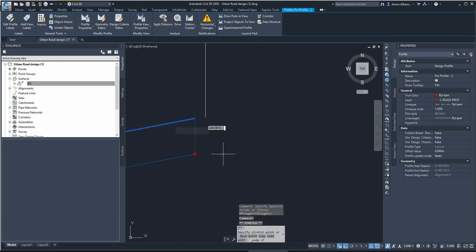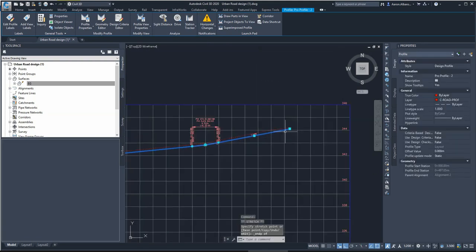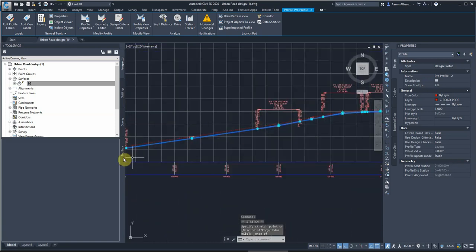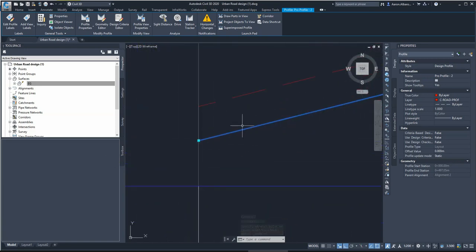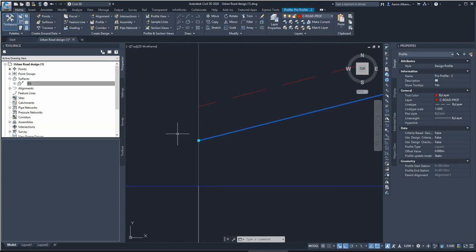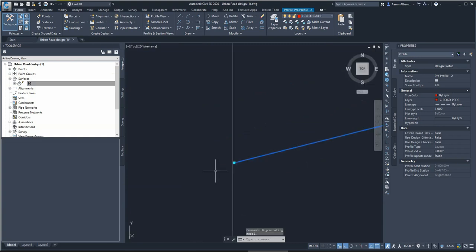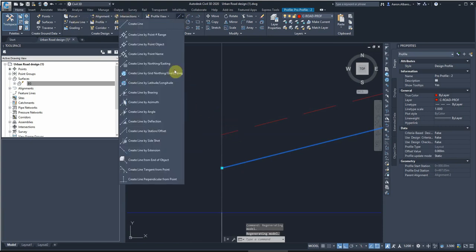Shift right click on it. I'll do the same here. If I keep that small line, it wouldn't hurt. Even if you can see it here, it looks perfect, but if you zoom in, usually it's not. So I make sure, see, there's a small gap there. I don't take chances, just make sure that you do it the right way.